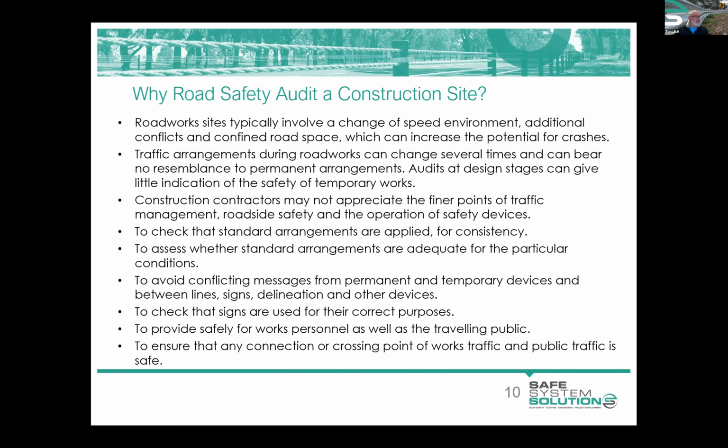And the last one on the list is the crossing points. Oftentimes they can be a little bit forgotten, in that crossing points can sometimes look as if they're an access point for the public, or vice versa, the public don't appreciate the crossing points and therefore aren't aware there could be construction plant coming out. So again, make sure that they are managed to ensure that they're used for what they're meant to be used for.